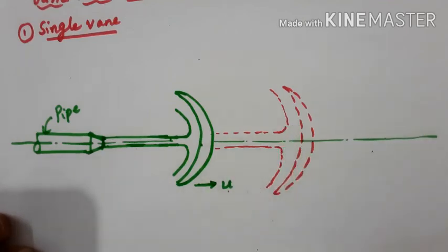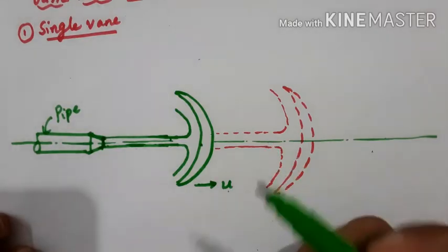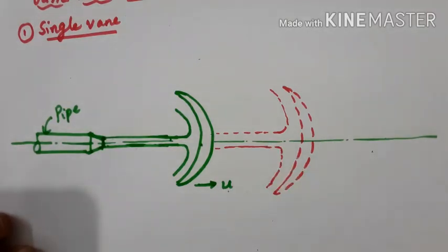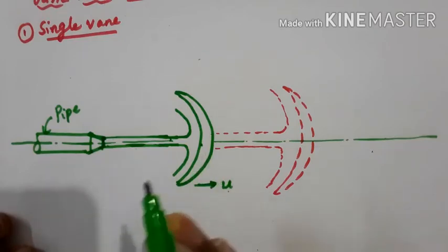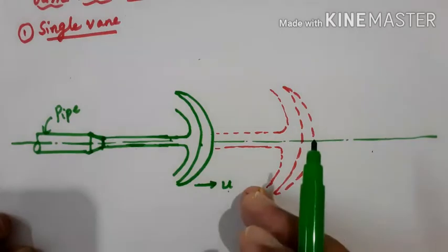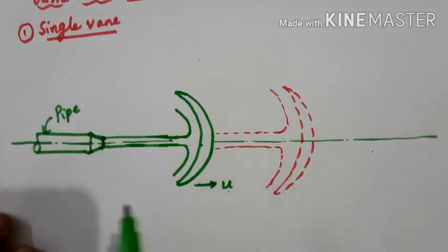Example, if you take the motion of a train with respect to the platform which is stationary, it is called an absolute motion, where the train is moving with respect to the platform, a fixed entity. If two trains are moving, say train A and B, then a relative velocity will come into picture. The motion of a body with respect to another body is called a relative velocity. So here in these cases we need to take the relative velocity.